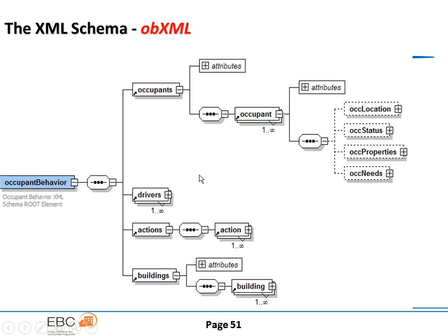Yeah. So let's talk about a few approaches to behavior modeling. For example, just take EnergyPlus as an example. I think other tools should be very similar. So we use schedules, right? Occupant schedules, temperature schedules, and ventilation schedules, and some predefined rules. Like in EnergyPlus, for example, shading. There are 21 rules you can define for when the shade can be open or closed, but still it's limited to 21, right? Maybe what you're interested in is not in the 21. So those predefined rules have certain limitations.